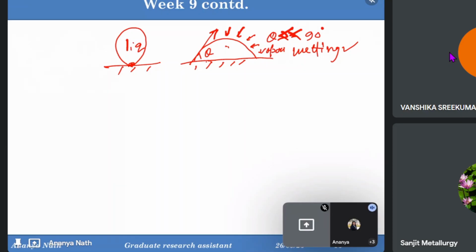Where we basically deoxidize the aluminum surface by molten aluminum, deoxidize the SiC surface, the disruption of the SiO2 film, and wetting through the Al4C3 interface. So the Al4C3 interface will help in the wetting of the SiC in the aluminum. But at the same time, Al4C3 is brittle in nature. I think it does have a hexagonal structure, but I don't remember clearly. But it has brittleness. So it will add a lot of brittleness in the aluminum SiC metal matrix composite as well.